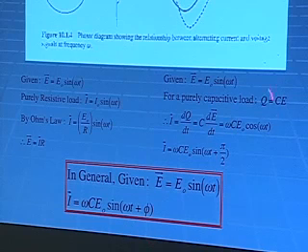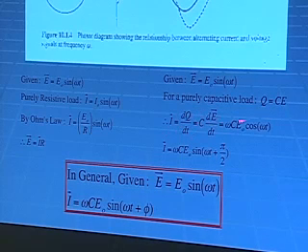On the other hand, if we have a capacitor, just using Q equals CV, then we have to take the derivative, assuming the capacitance is not time dependent. We come up with a cosine function and a frequency dependence in the linear part of the curve also. Or just rewriting that, since this is a sine wave, we have a 90-degree shift in our sine wave plus this additional frequency dependence.